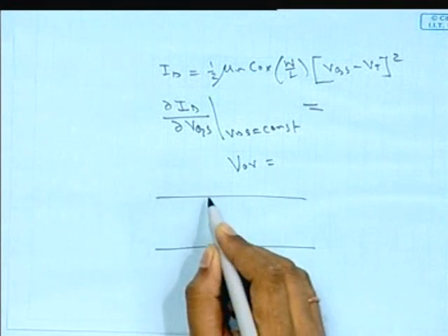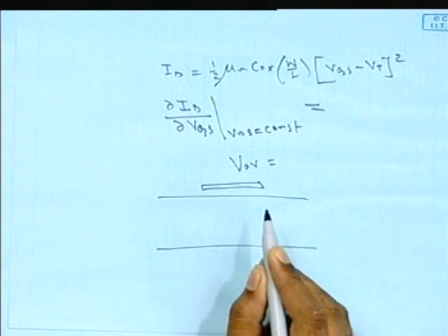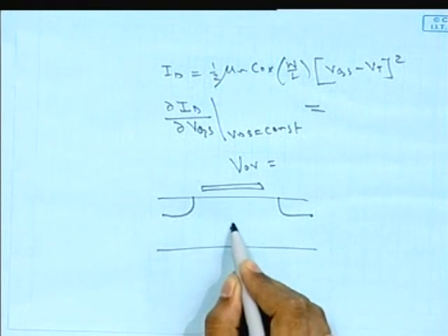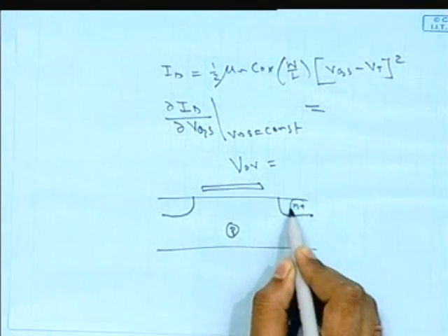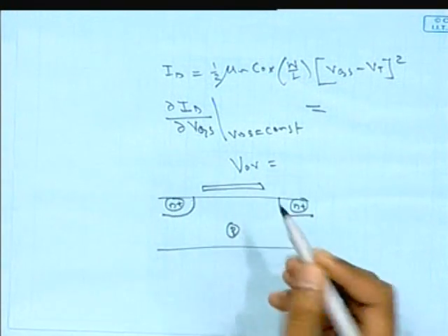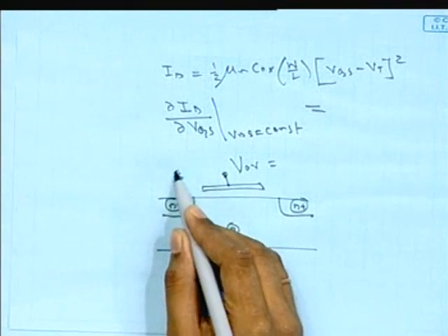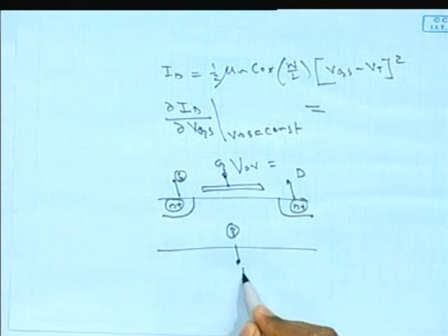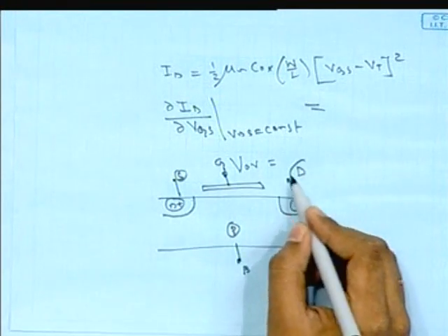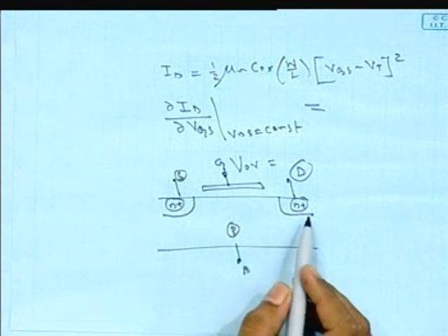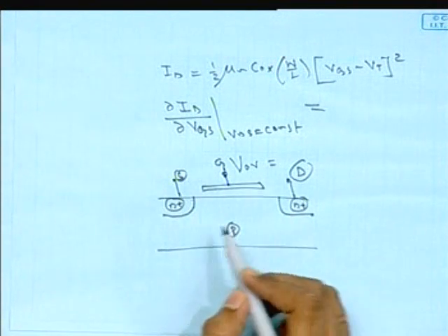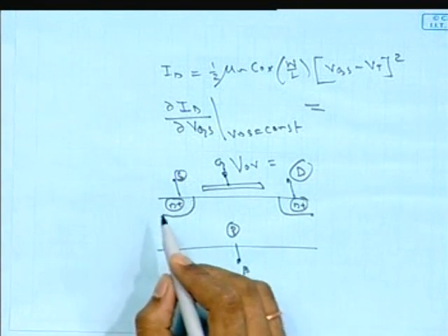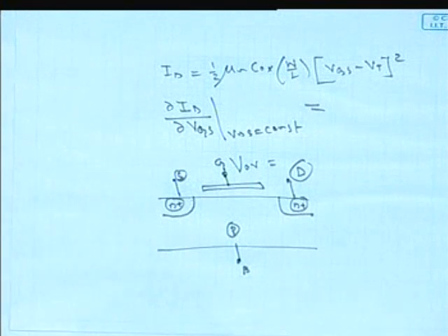Now the structure or the schematic of the MOS device is like this. Okay, here we are seeing the N plus region of the source and the drain, and there is a P region which is nothing but the bulk region, and we know that if there is an N and P region, there will be some junction capacitance in between them.